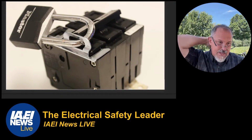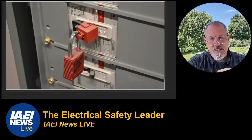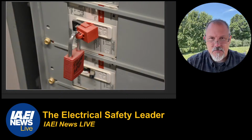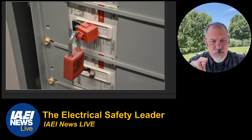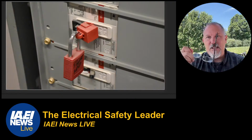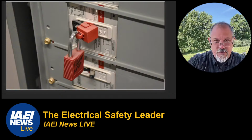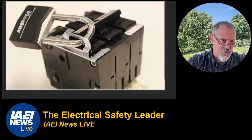And yes, okay, so the tag is now for the identification of the owner. Robert from Omaha, yes. And in this case, this lock has a name written on the side of it. And you say, well, that's not permissible, Tom. Well, if you read the rules closely, you're allowed to do this within a shift, maybe a short period of time, that type of thing. It's not something you're going to leave in place for a long period of time. So there are provisions that this could be a legal application. But again, you've got to follow the details of the rules.